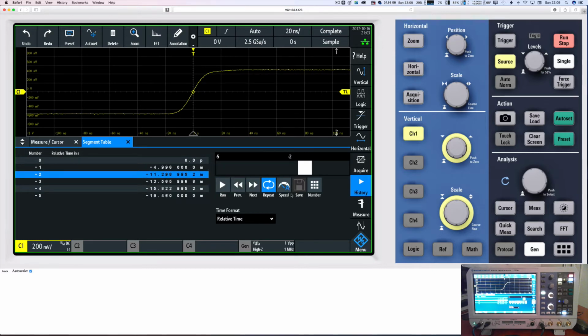You can also save, if I had a memory stick in, the waveforms here that you've captured. And there's also an option to do relative time. So these are the times, the difference in time between each capture, or you can do absolute time, which I think records the actual physical time that's on the scope itself, all the way down to about 7 positions past the decimal point.